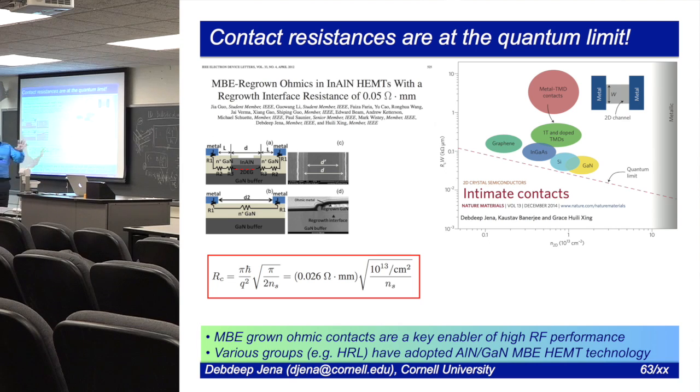And just to be sure, this is the quantum limit for crystalline material. Right? So there's maybe a hint there that if you make it somewhat partially non-crystalline in some regions, you can maybe break this limit. We don't know yet. For any material system, for example, today a lot of people are working on these transition metal dichalcogenides like molybdenum sulfide and selenides. The resistances, at least till 2 years ago or 1.5 years ago, were very, very high, 2 orders higher. Now they're about 1 order higher, but there's still a long way to go.